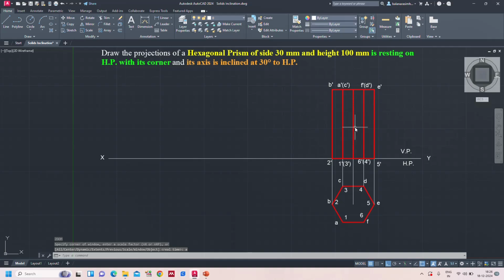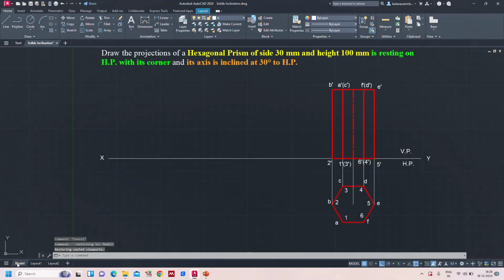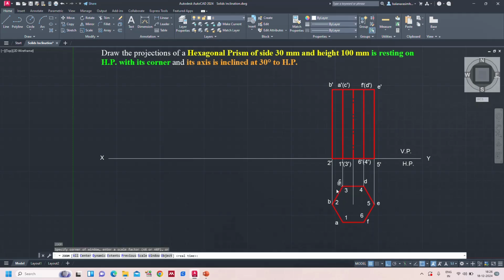Right now this is the axis line, line type scale 20, only for the model space. Whenever you want to see in the layout, please don't use line type scale 20, go for 0.5. Just for the visibility here I took it as 20. Keep it in mind. Now the stage 1 got completed.